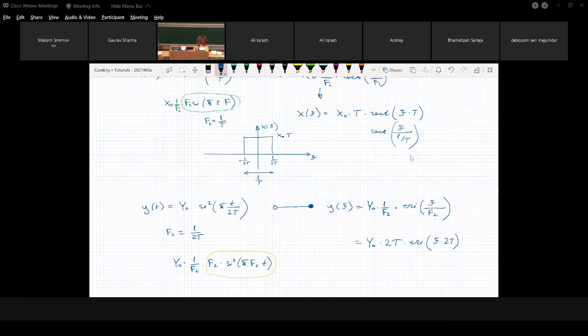Okay. But anyway, usually we assume that at the second stage, you have this fixed carrier frequency, and it's done by just the value of frequency for your carrier frequency oscillator. And then by changing this intermediate frequency in the digital domain, you can decide at which position in the frequency range you place your signal.